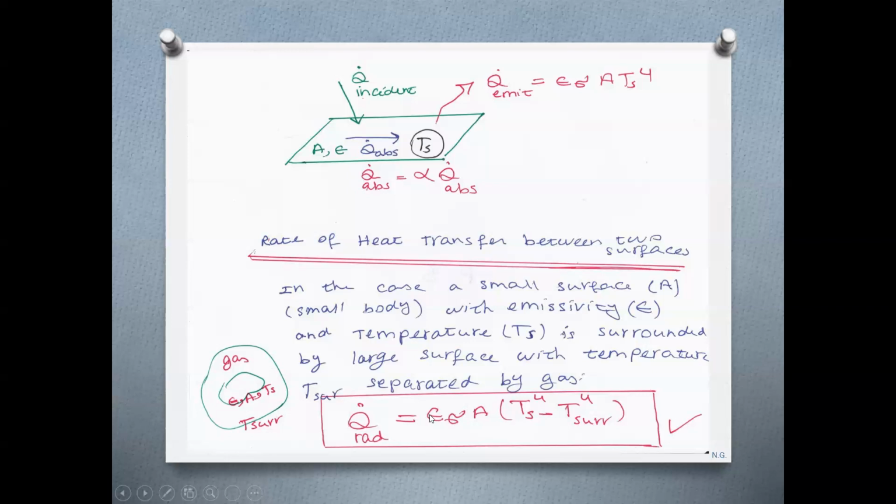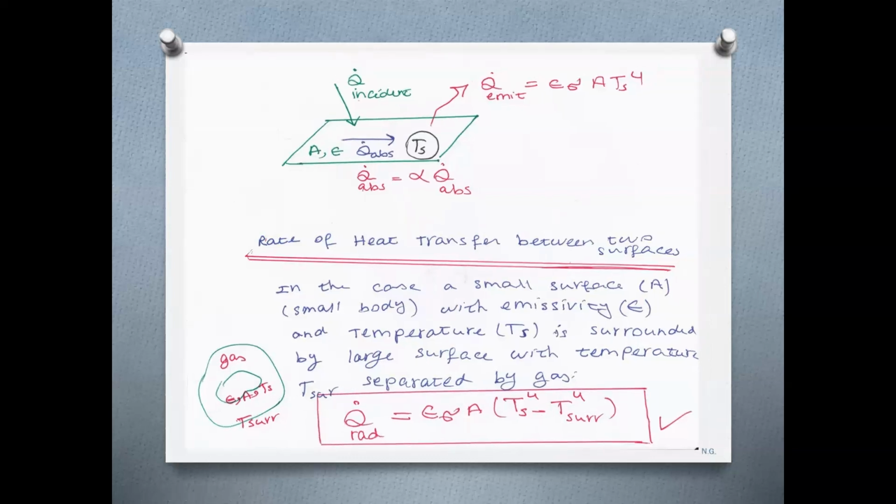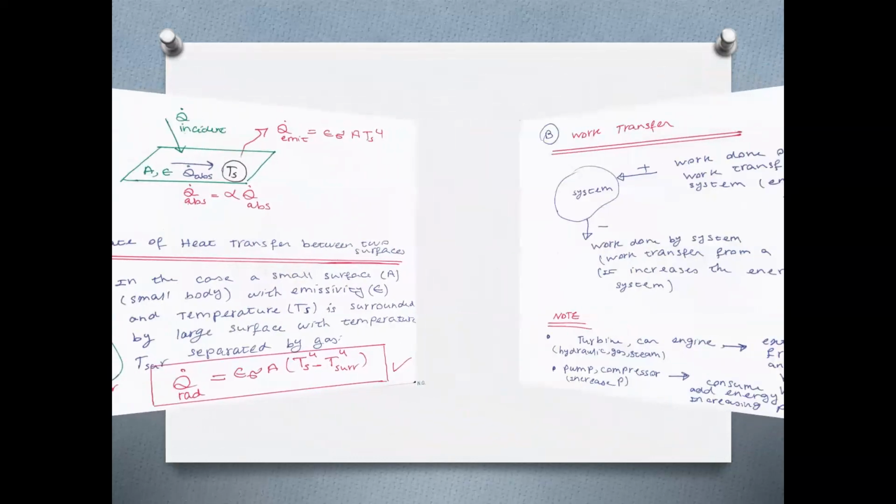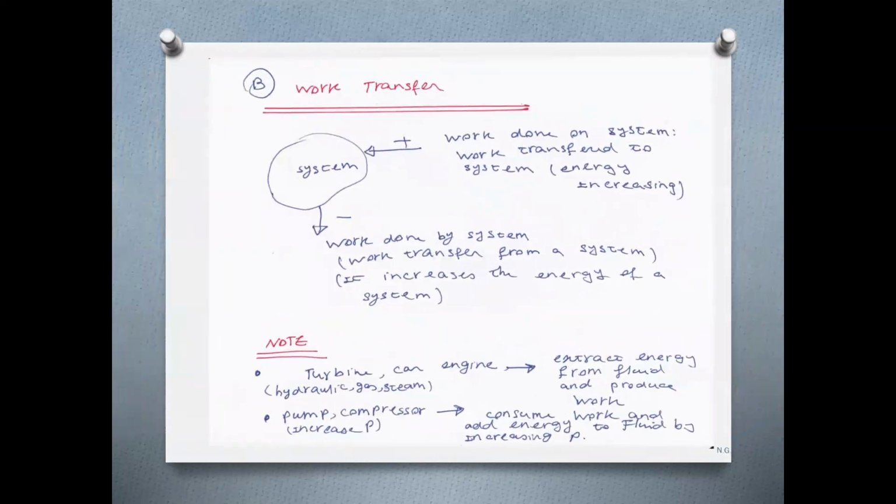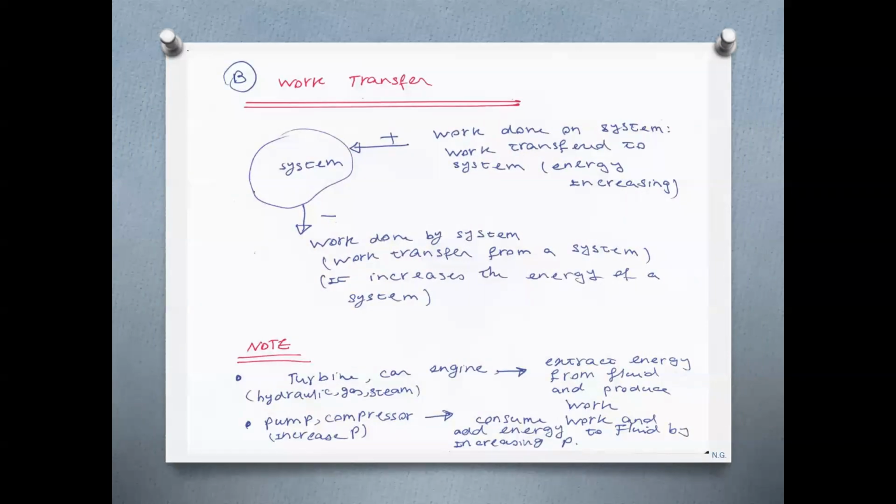So this is the emissivity of the body, area of the body, a Boltzmann constant, surface temperature of the body, and temperature of the surrounding. And that is the rate of heat transfer. Q dot is the rate of heat transfer by radiation to or from the body. To the body, basically. But if you come up with a negative value, that is from the body. So it can be heat gain or heat loss, but that is net.